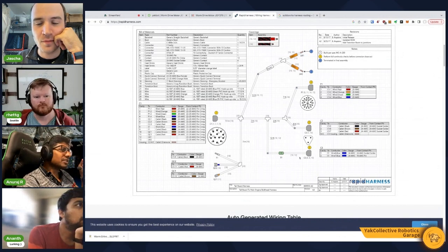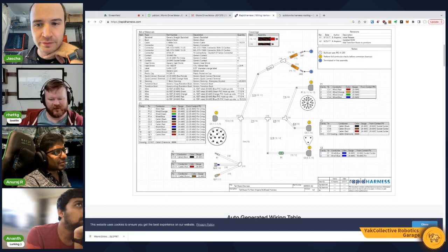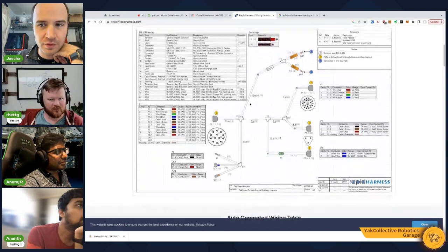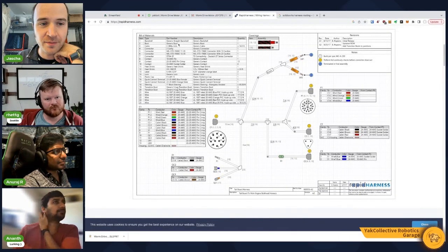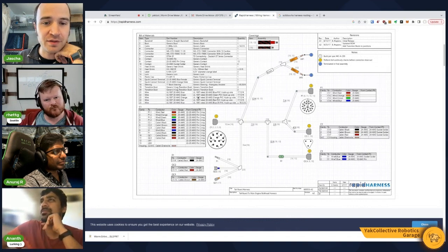So how is this used on the shop floor or in production? This is ultimately the document that controls the product that's being delivered. This is the spec. Okay. So those individual connectors at the end are potentially off the shelf, and it's all the sizes and the number of conductors and where they all route to. Correct. So, just to go over this, on the upper left, we have the bill of materials. This specifies the part number for each and every wire in the harness, the covering on the wire, and the connector at the end of the wire. Every single part is defined down to each individual wire.